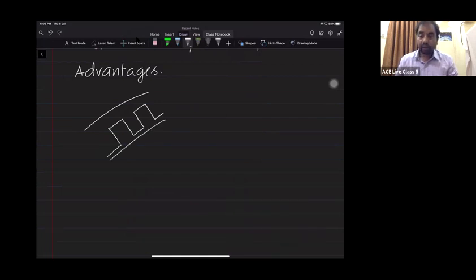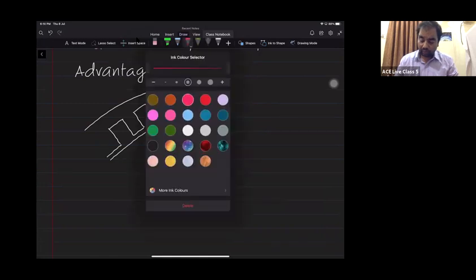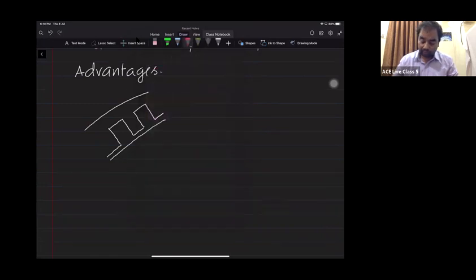So under the teeth, the reluctance is less. When the reluctance is less, more number of flux lines will be passing under the teeth like this. And you can see there are no flux lines passing through the slots. Why? Because air gap is too large. The vertical length is too large. Is it clear? Confirm me.